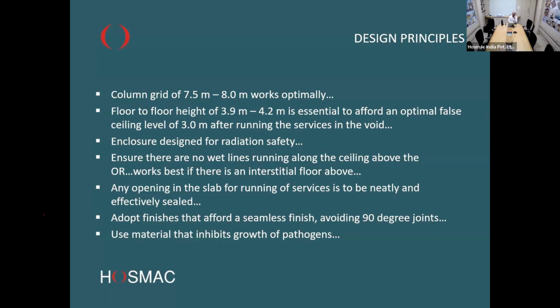Likewise, when we do need to take openings in the slab for running the duct work and other services, any opening in the slab has to be neatly and effectively sealed. Very often we have seen instances where service slab cutouts are done, but if they are not sealed and closed very properly, they become a source from where rodent movement and other infestation can move in. You may not see it below the false ceiling because you have a very neat false ceiling in the operating room, but things start accumulating atop the false ceiling, which of course is not acceptable. So this is something that we need to bear in mind when we're planning and also when we're executing. We should be acutely aware of this.